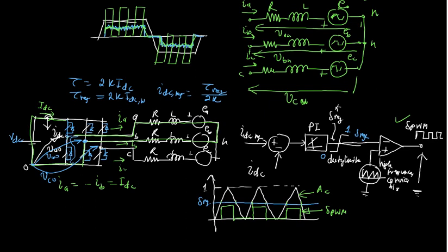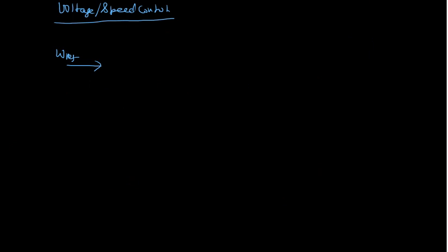These things we have seen before. So similarly for the speed control, that will come in terms of voltage control. So you set a speed reference. I am now talking about the conventional motor controller which is widely used in the market at present. So this is the speed reference, and then you feed back the speed. Feedback is there. And then again you use a PI controller. You see the strategy is the same. PI means proportional integral controller. Can I write here?